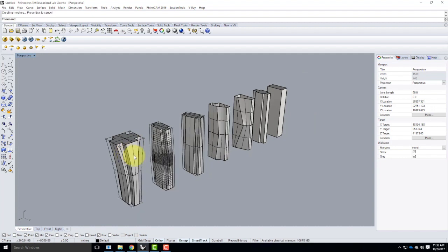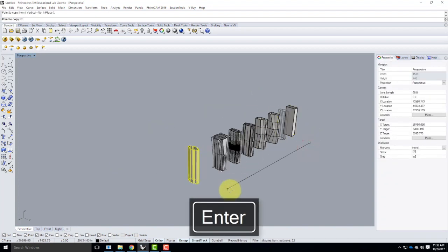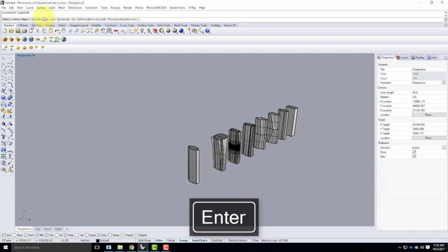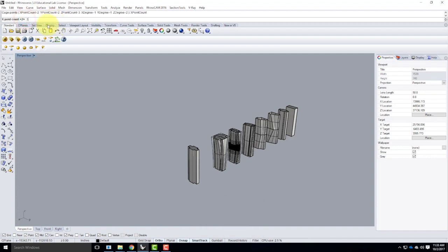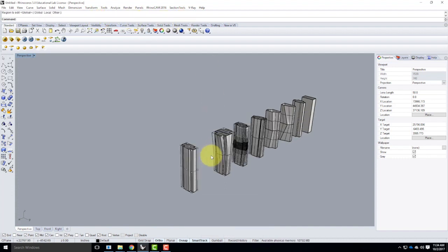You get the idea. So as I'm going through and transforming these objects, I'm starting to play around with them. Now, if I take the same object, and we come over here, and I do a cage edit again on it, bounding box, world. Okay, I'm going to change these all up to 3. So x is 3, y is 3, z is 3. My degrees are going to be 2, and 2, and 2. I'll hit enter. You'll see that I end up with more control points.